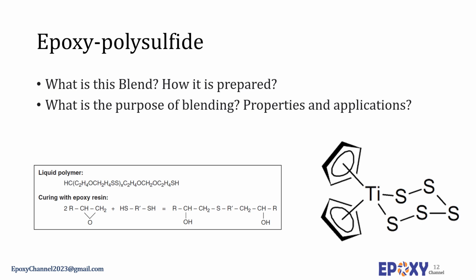The addition of the polysulfide resin acts as both an elastomeric modifier and a diluent for the epoxy resins. The low viscosity of these products can drastically reduce the viscosity of the overall formulation. This provides greater ease of mixing and application and the ability to be applied and sprayed without a solvent.